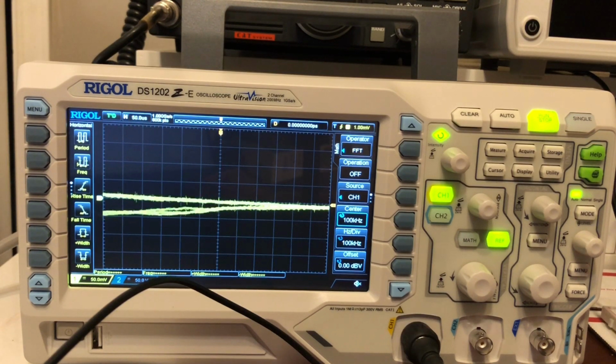So it says you can choose under window function. Rectangle has the best frequency resolution and the poorest amplitude resolution, similar to the situation when no window is multiplied. Blackman has the best amplitude resolution and the poorest frequency resolution. Hanning has better frequency resolution and poorer amplitude resolution compared to rectangle. Hamming has a little bit better frequency resolution than Hanning. And for accurate measurement of signal amplitude, there is flat top. And then triangle has better frequency resolution.